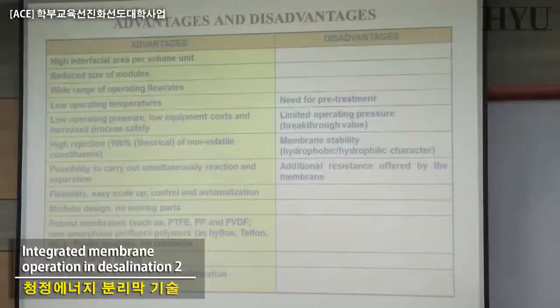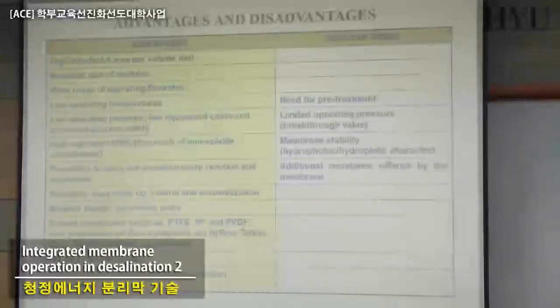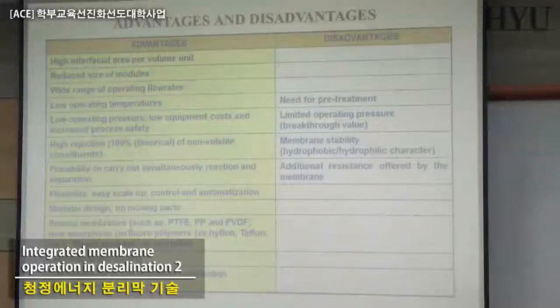Most of the MBR processes were ultrafiltration, no more. Today, if you go in the literature, and some of you will be involved, you can have, for example, membrane distillation combined with the biological treatment. In the submerged MBR, you don't submerge UF, you submerge MD or NF, etc. So these processes are also quite interesting for some new applications, and that's important.